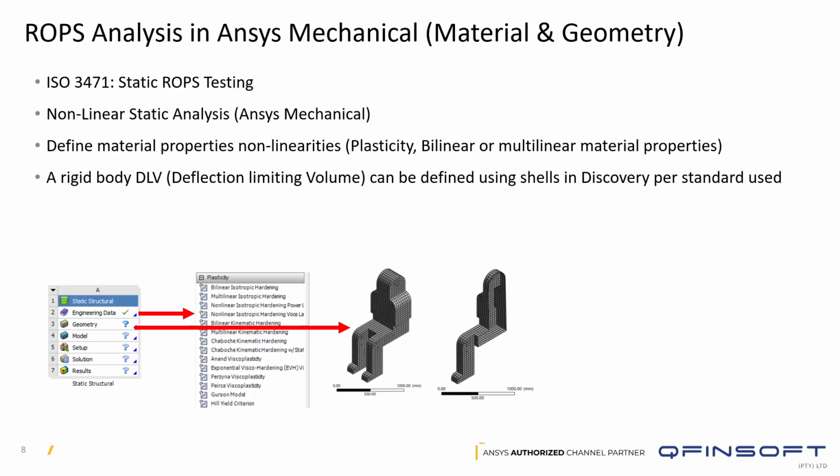Okay, so first we'll be looking at how we can handle testing cabins or machines for ROPS inside of Ansys Workbench using Ansys Mechanical. For this case, we'll be looking at the standard ISO 3471 for the static ROPS testing. The first thing we'll need to handle when looking at ROPS inside of